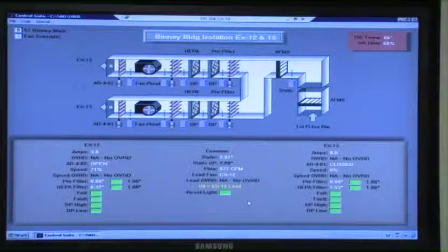So what ends up happening is that a light on the front of the panel will illuminate, requiring a reset. The lead fan that runs and fails, say it trips on a static pressure or something, is going to command the fan off because the static is tripped. It's gonna light this light. That gives you an alarm that a manual reset needs to take place. The person's gonna go up to the fan, find what it's tripped off on, low static, hit the reset button on the static, and then push the reset button on the front of the panel, and it will reset the process. Okay.